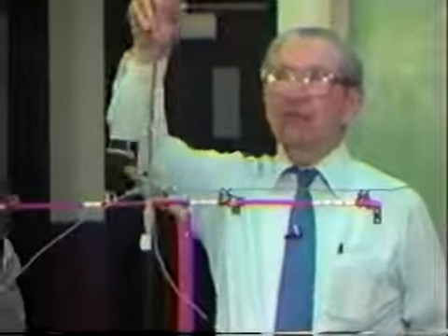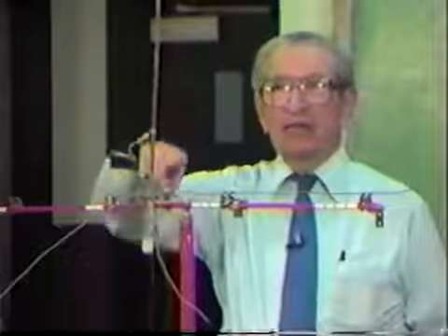And we're going to examine this antenna with a little care and see what we have here. Because here we have a situation where we're using a ground plane, where these four pieces of metal are quarter wavelength long in an opposite plane to the vertical itself. And these wires here are not looking at themselves as part of the antenna, but rather as part of the antenna system.